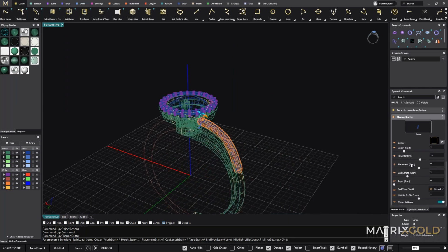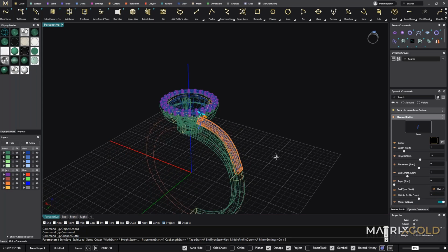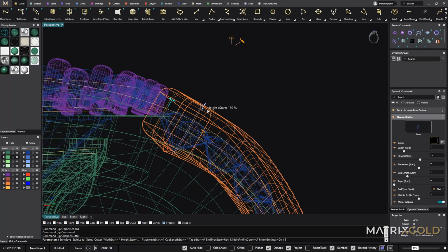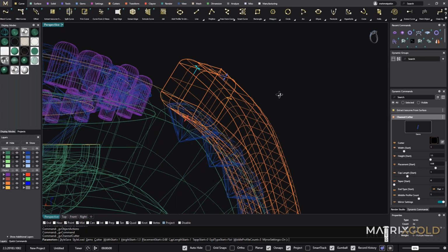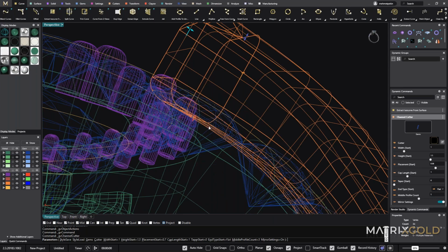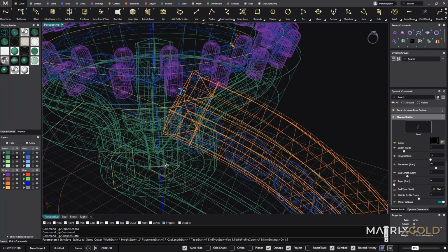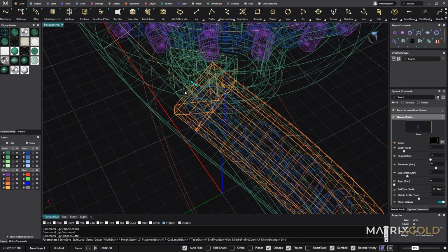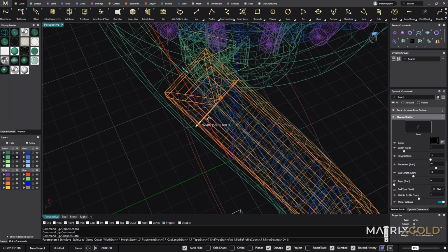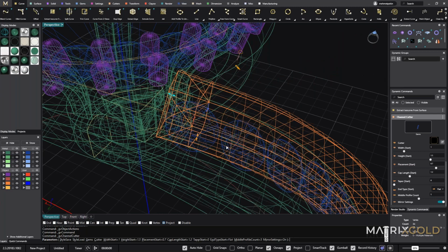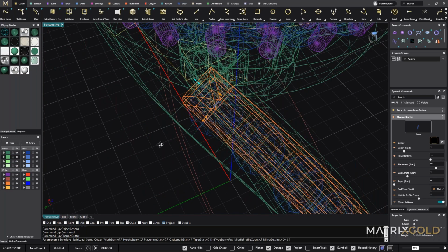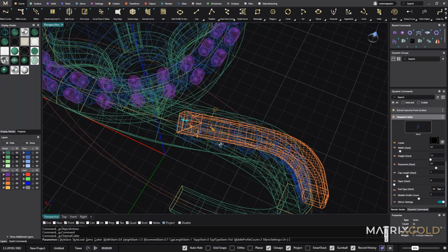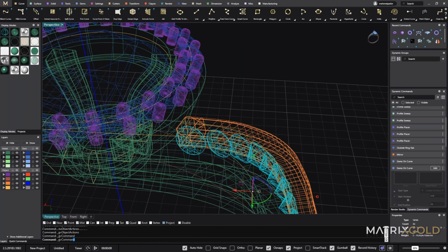I'm going to use not round, I just use flat for that part. And I want to move to here with that button, like this. And I want more spacing from here. It's not important because we don't use prongs with that part. Maybe something like this, and I want to make it a little bit narrow. Now it's okay, and then select again the gems and select micro prong cutter again.